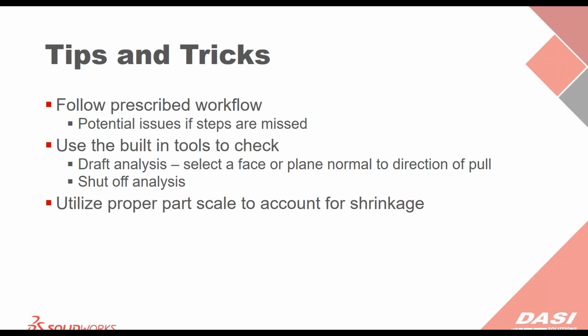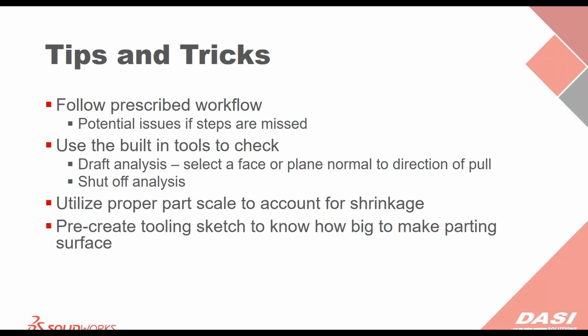Utilize the proper part scale to account for part shrinkage. Of course this is based on your material, but it's nice they have that quick scaling tool just to add that in. Pre-create your tooling sketch to know how big to make the parting surface. We talked about this a little bit. If you already know how big you want your tool, your cavity and your core blocks to be, you'll know how big to make your parting surface.